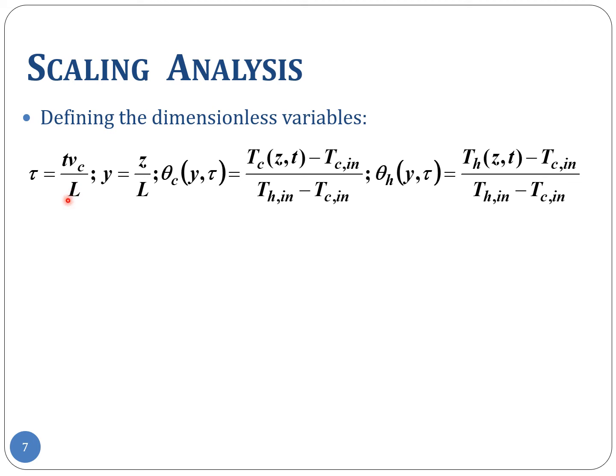So we have taken this characteristic length for the axial flow, which is of course L, and the characteristic velocity for the axial flow is constant here. It is the plug flow velocity Vc. So L by Vc will give a time, and then t, which is the real time in absolute units, 1 second, 2 seconds, 3 seconds, and so on. When you take that t and divide by the characteristic time L by Vc, you get a quantity which is a dimensionless time.